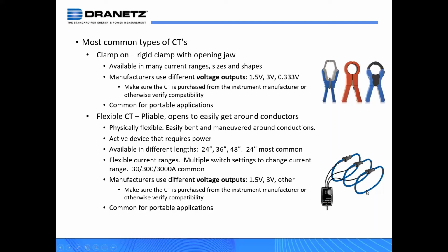Just like you're monitoring voltage, monitoring current, I should say, you're monitoring current during a voltage event, and then depending on what the relationship of current during the voltage event, you can determine the origin of the voltage event. Same applies for transients, except that we're dealing in a much shorter time frame.